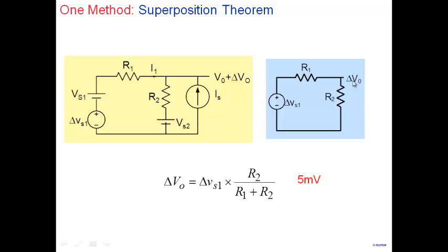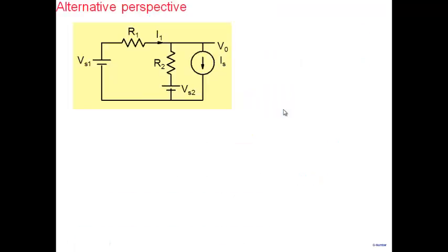Anyway, another way that I can get this particular answer is similar, but in the following manner. Just to illustrate an alternative way of arriving at the same answer here. So as you can see here, this particular circuit is there. We have described this particular circuit in terms of these equations. Vs1 is I1 R1 plus V0. That's this part here. And I1 that you see here is equal to Is, KCL here, plus V0 minus Vs2 by R2. Straightforward equations. So that's for this circuit.